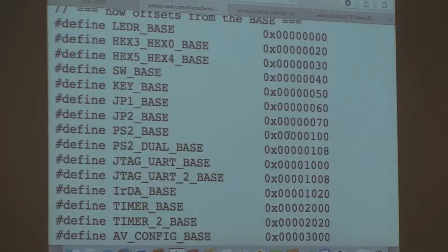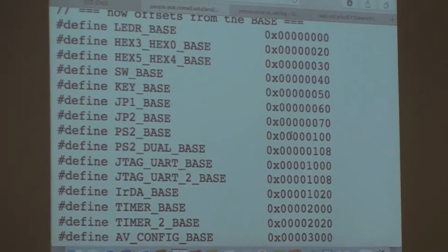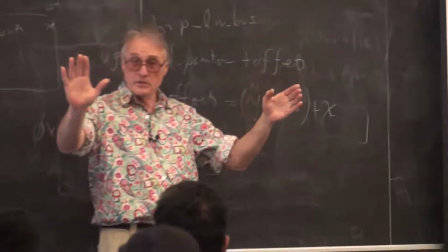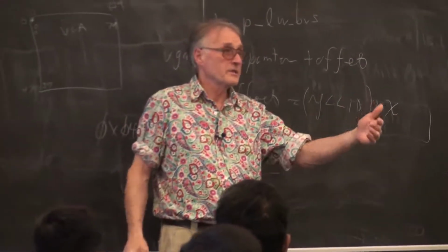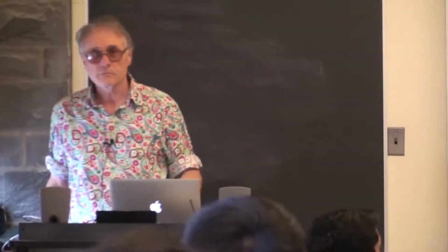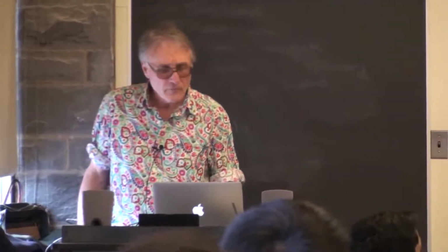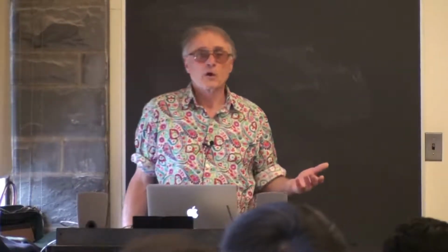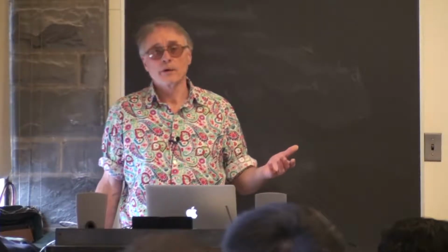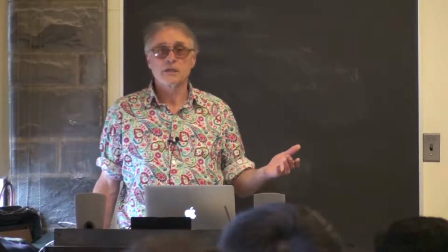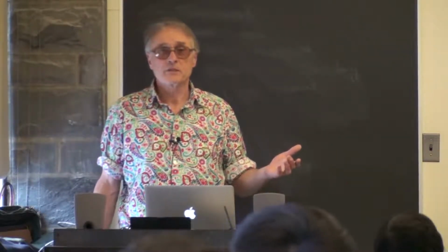Because they have to agree, right? The bus addresses assigned in Qsys, where you get to type them in, have to match this file, which is what C is going to use to generate the accesses to those addresses that you defined in Qsys. Does that answer it? Yeah. So in your C code, you're going to do a write to the value of the pointer, which is the hardware register base plus switch base.